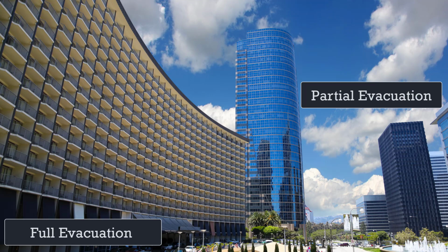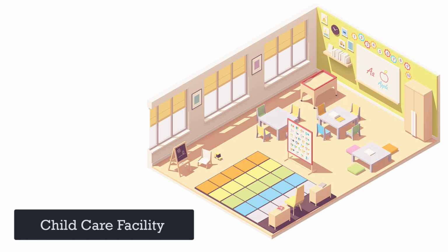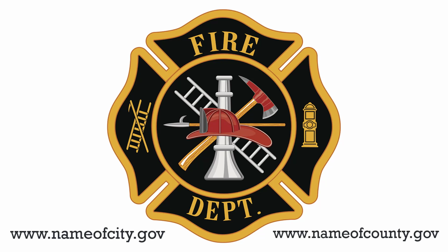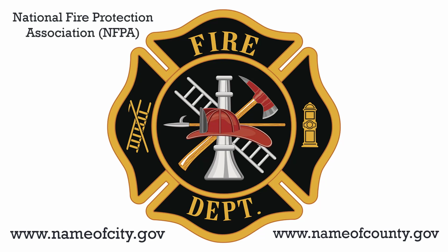For example, fire and evacuation drill requirements at an office building is typically 2 times per year, whereas frequency at a child care facility might be monthly. The building's life safety director should confirm fire and evacuation drill requirements by reviewing the fire safety section of the AHJ government website and follow up with the fire department. Additional codes, regulations, and resources may be referenced through the National Fire Protection Association.